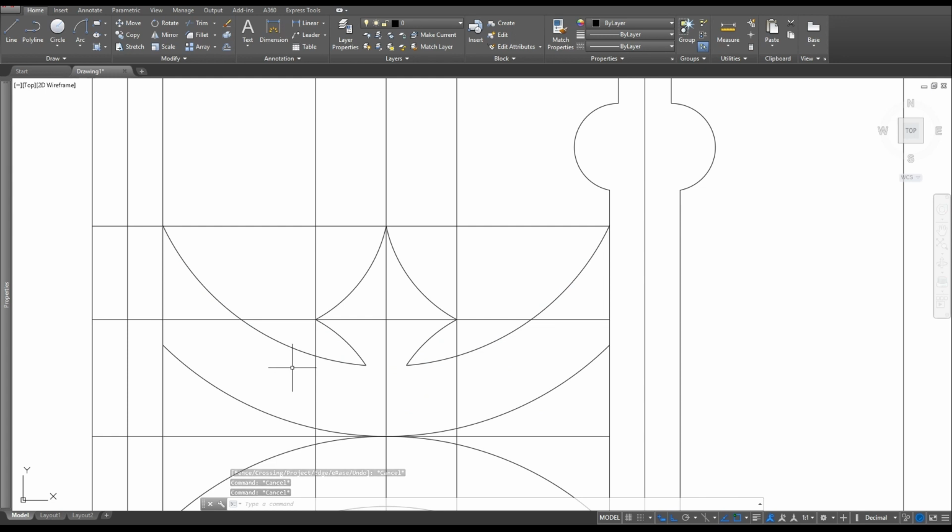It tells me what radius that it wants on the inside of those. And that's going to be our 1/8 radius there. So if I choose the fillet command, change my radius to 1 divided by 8, you'll see that this will actually bend the way you want it. So I have this shape created.